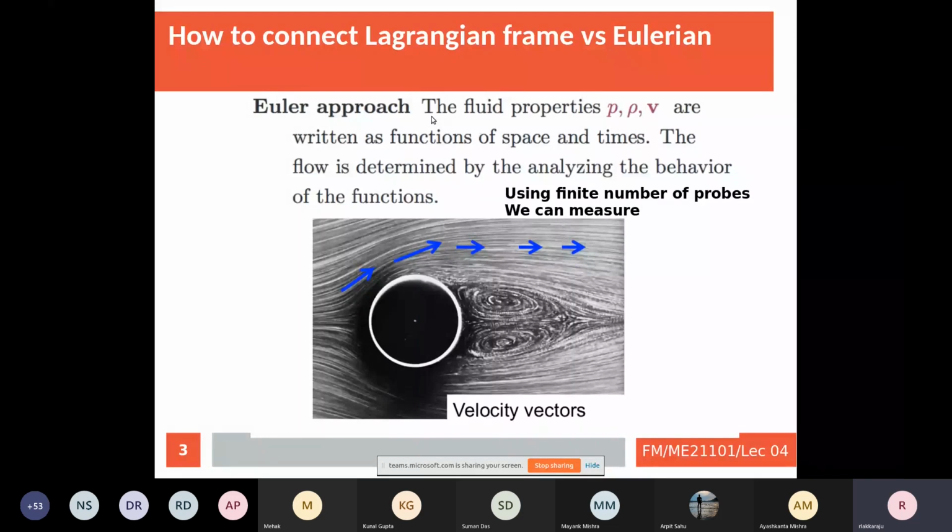So naturally, there will be a change in resistance in that probe. And you calibrate the change in resistance with respect to how much flow is happening. In that way, one can measure the velocity of the system. Especially in liquids, you keep something like a probe which has a tungsten filament. You have a battery to heat it.